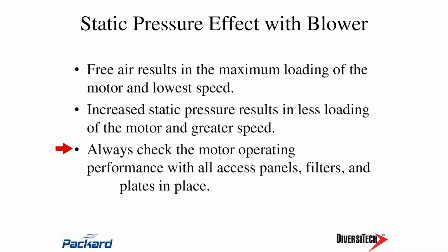Make sure all the doors, panels, filters, guards, if that condensing unit is under the deck and there's a trap door to access it, you've got to make sure all of those things are in place when you're checking the amps of that motor to make sure whether it's operating properly or not. So those are important characteristics to consider.